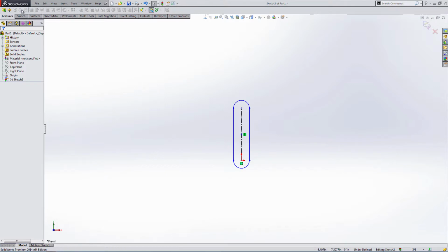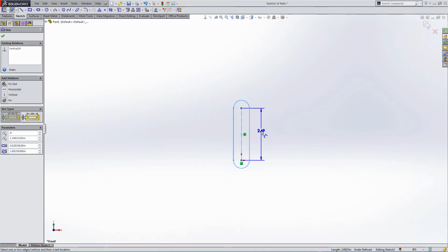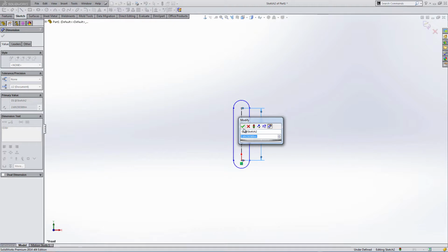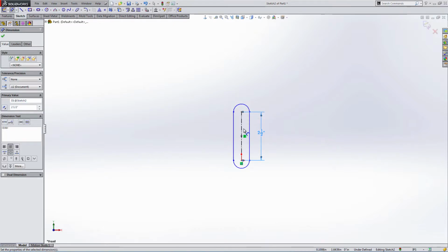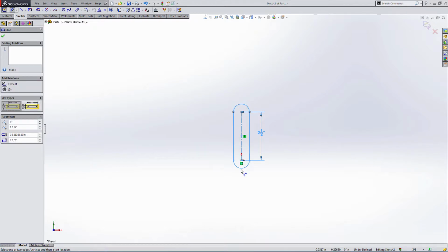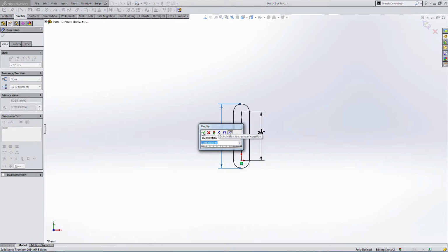And if you're working in a fab shop, you'll get guys with different preferences on how they want these dimensioned. Most engineers are going to dimension them center to center because that's how much the bolt can travel. But I've noticed there's a lot of fab guys at fab shops that want it dimensioned outside. So I'm holding down the shift key here, and that's how you get the outside points.